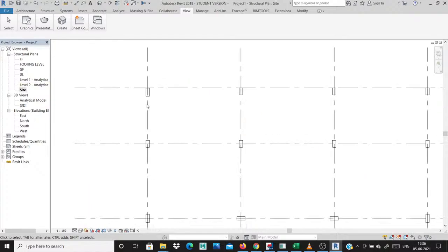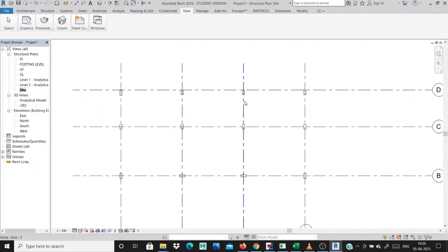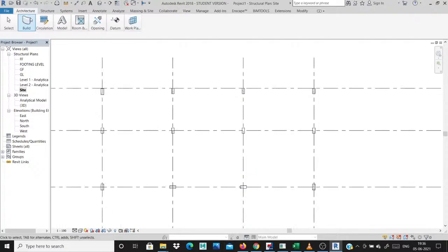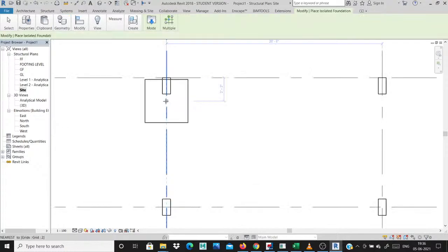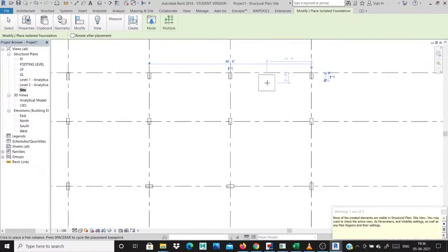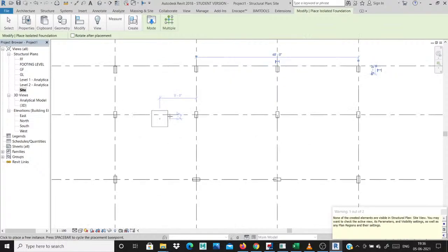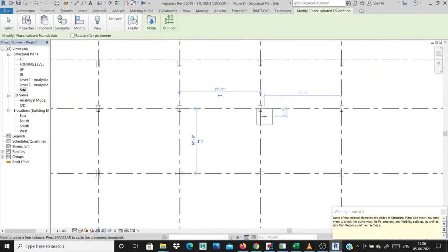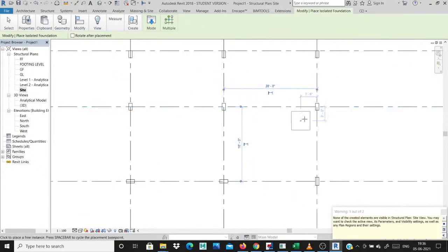Since I created all the footings the same way, simply go to architecture, structural, go to footings. This is our eccentric footing. See this, I simply created the center point and provided this eccentric footing. This also I provided as an eccentric footing. This also. And this is also a normal footing, isolated normal footings also.